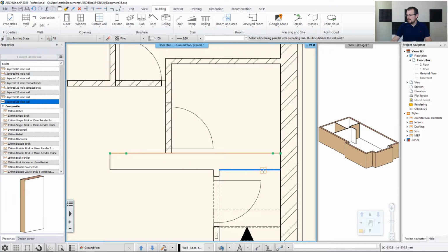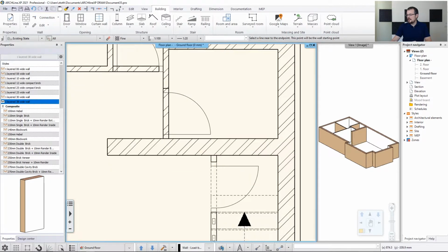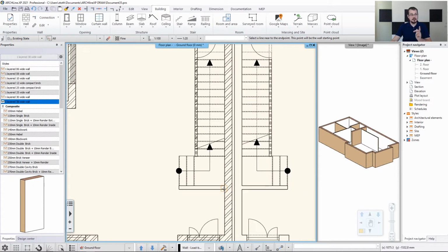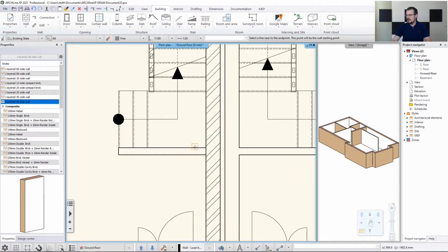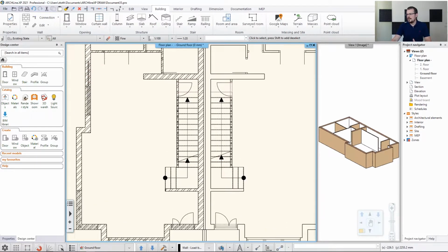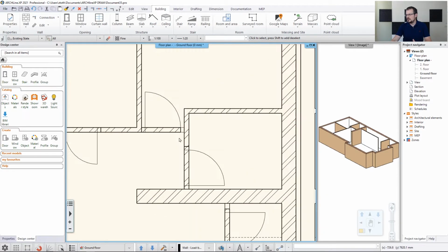And just click on the ending points and the thickness, and then the software would give you exactly what you need. Now, there's going to be one special case over here. I'm making a mistake here intentionally, so later on I can show you how to amend that, how to correct that. So click, click, click. Now, I think I have all the walls done correctly, but there are two issues. One is with the T connection over here.